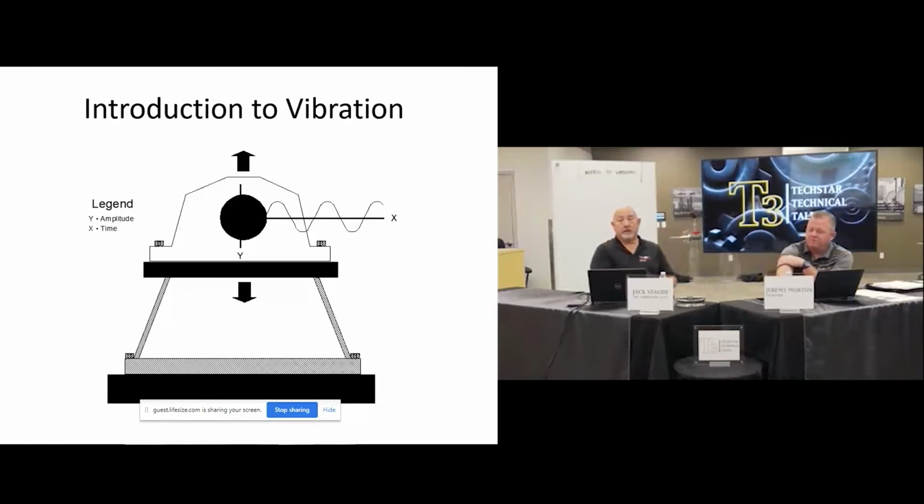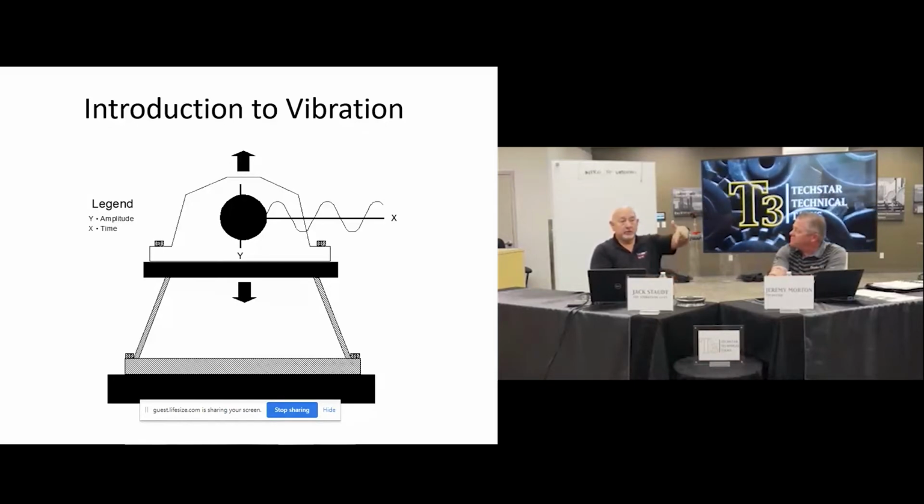A lot of people never knew this about Bentley Nevada systems, but no matter how you look at your probe, this is always going to be your Y probe, this is going to be your X probe. And you're looking from the driver to the driven. Yeah, so the motor to the pump.